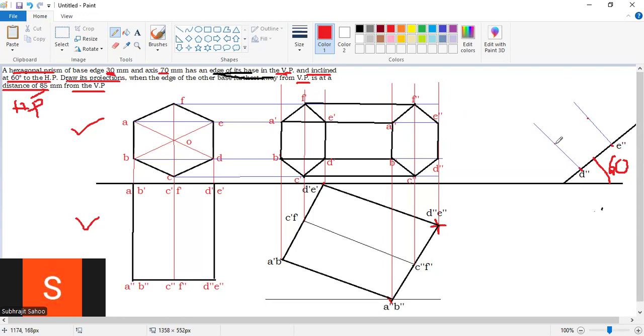Right. What are the points here? B point. What is the point here, sir? A point. Sir, F point is required. C point is required. Very simple. Take the D to C distance and draw an arc this side. And the B to C distance, this is my B point. Draw an arc this side. Now join here to here. This is my C point.